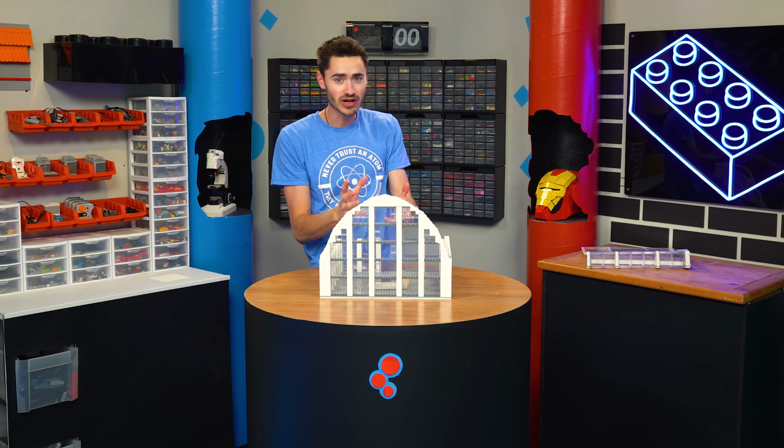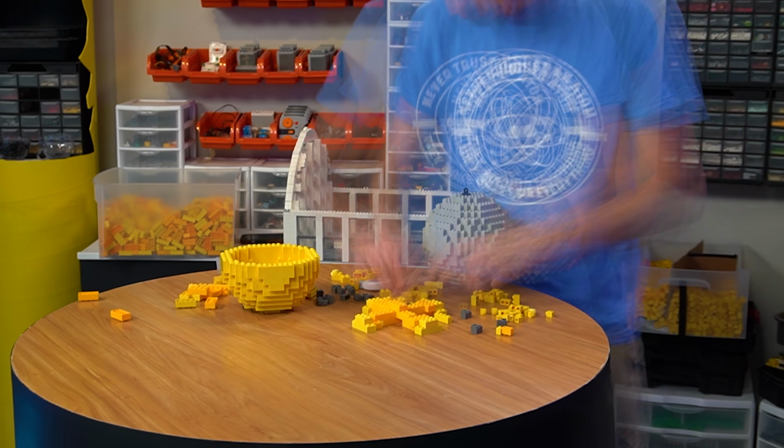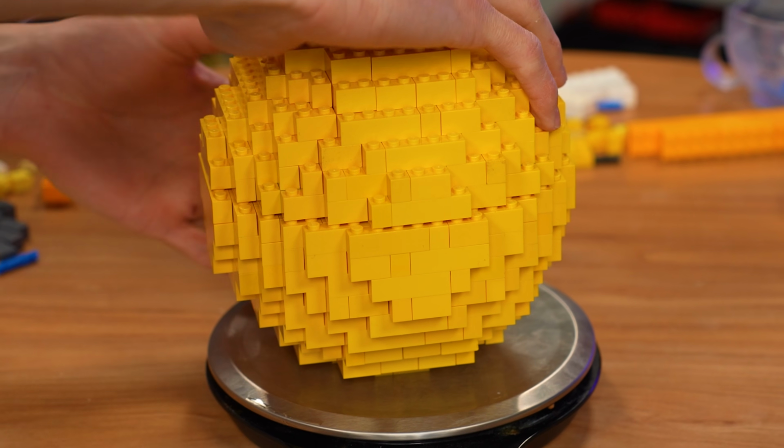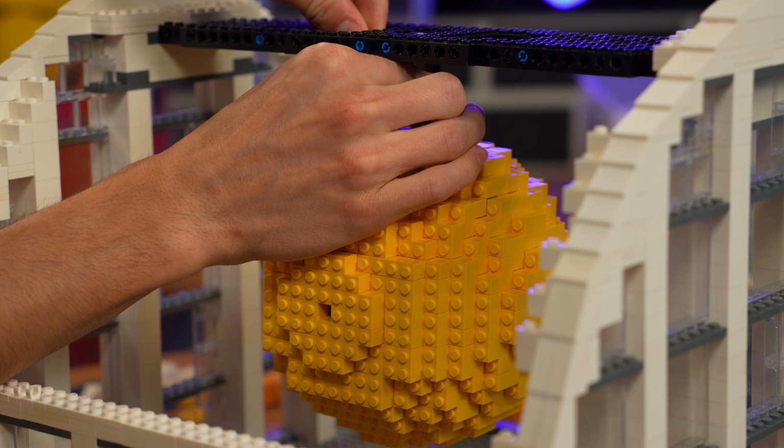So I'm gonna start building up a Lego ball out of yellow pieces that we can fill with weights to act as our TMD. And since this will basically work like a pendulum, we're just gonna build a tightening system at the top so that we can tune it to better match the frequency of the building swaying back and forth, also known as the fundamental period.